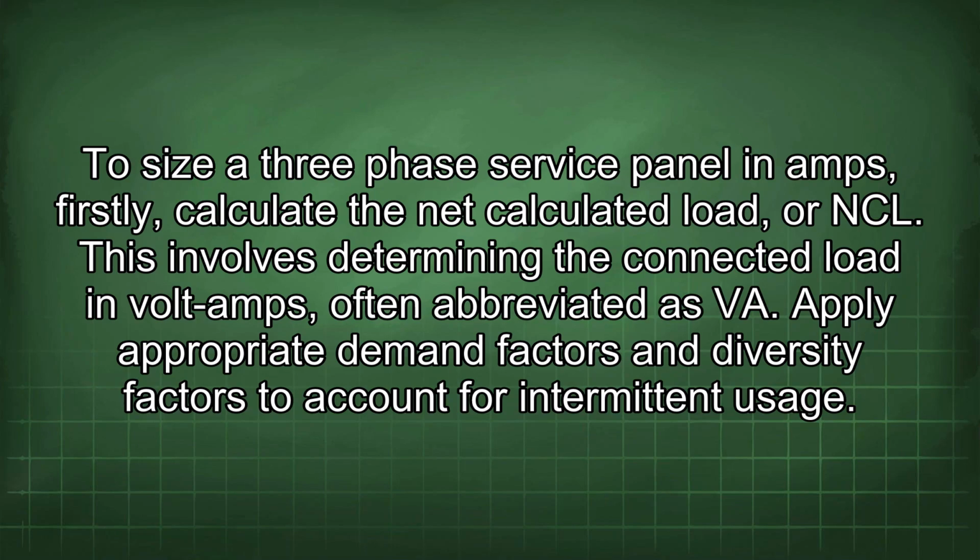To size a three-phase service panel in amps, firstly calculate the net calculated load, or NCL. This involves determining the connected load in volt-amps, often abbreviated as VA. Apply appropriate demand factors and diversity factors to account for intermittent usage.